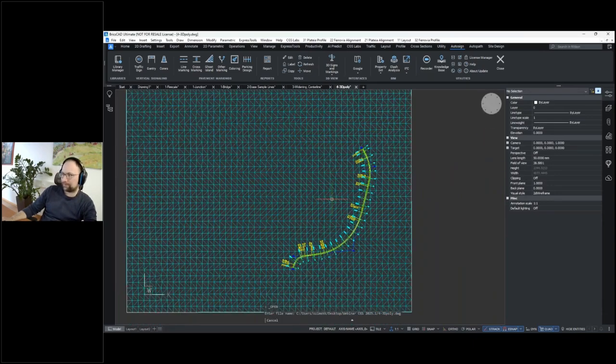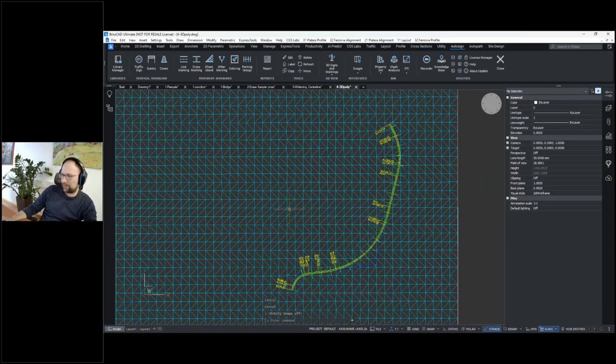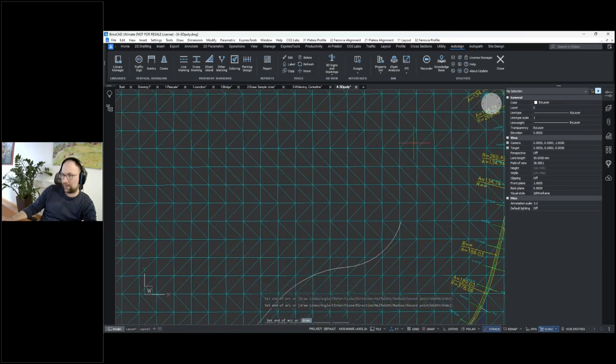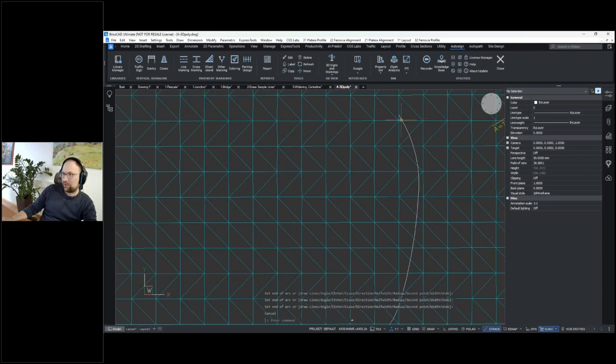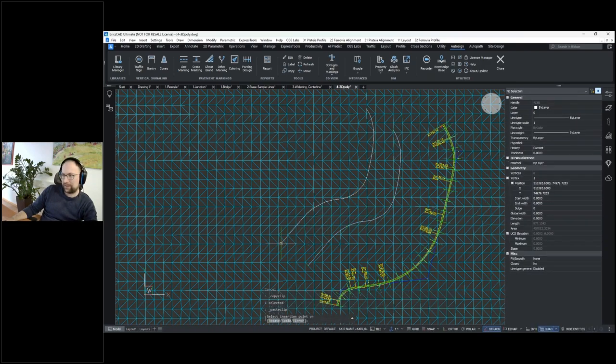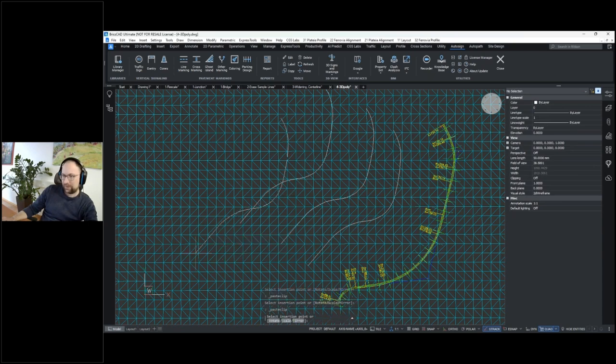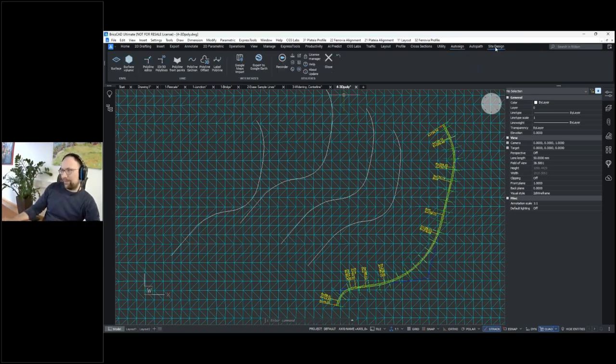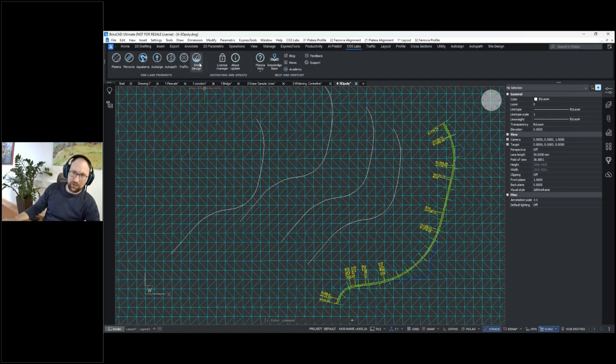Okay. So I will just create a polyline. This is more of a common tool which you can use for various different things, like finding the position of pipes or something like that, where you need to drape something on the surface. So I will go to the site design ribbon tab, which is also available in the common ribbon tab here.